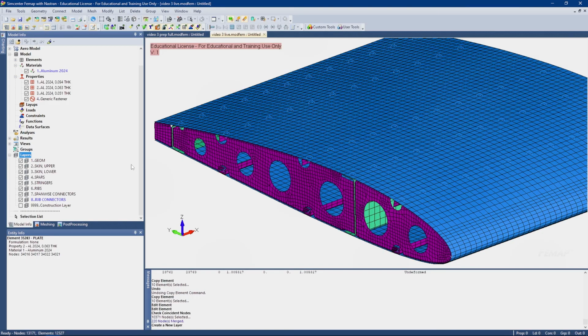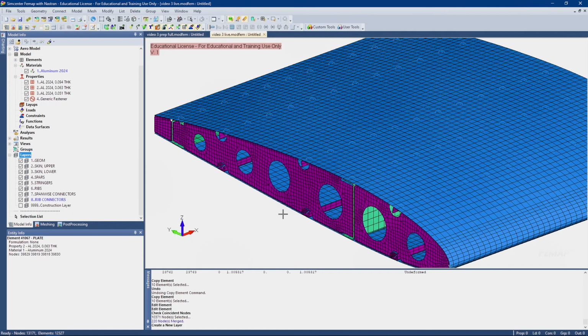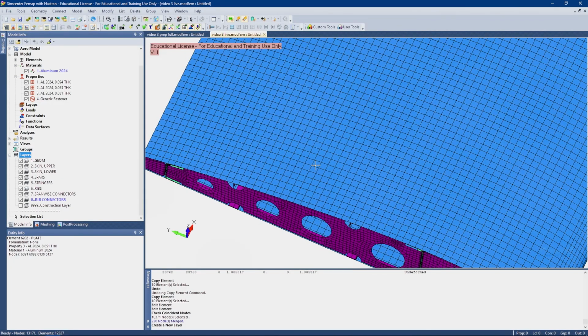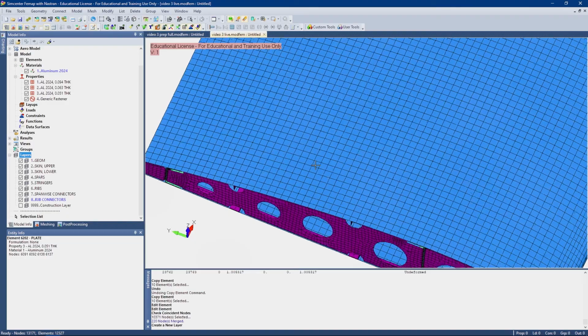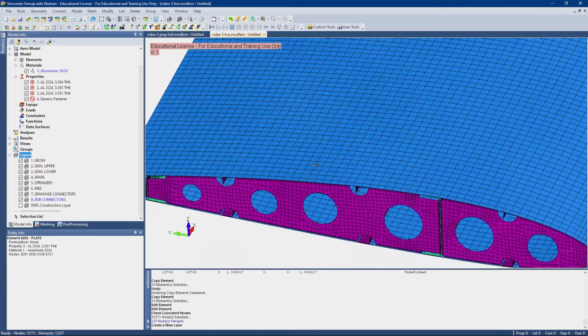However, essentially what we're going to do is determine the position of fasteners based on the mesh. If we wanted to determine the position of fasteners in our model and then mesh that, then we would have to put some sort of feature or cut in the surface to tell the program, hey, I want a node here, so I can add a connector, and then it'll do that. Also, one thing I generally do, if I have holes in my model, I'll fill those holes with a surface but leave the outline of the hole, and then you can add a node to the center of that surface and then remove the surface using FEMAP. I'm sure I'll do that in the future in some other video.